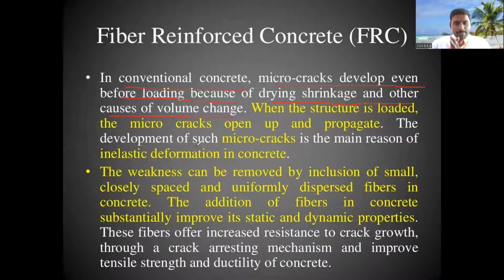This is a very important sentence we should know before we learn about fiber reinforced concrete. Microcracks are developed even before loading because of drying shrinkage. So shrinkage will happen, and due to that shrinkage, cracks will develop in the conventional concrete.